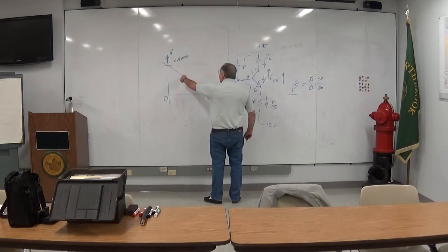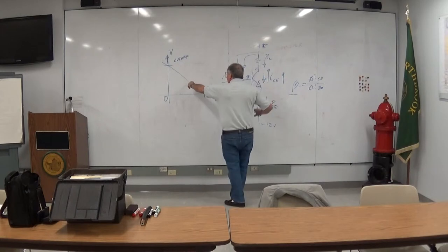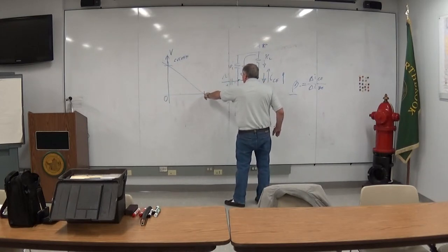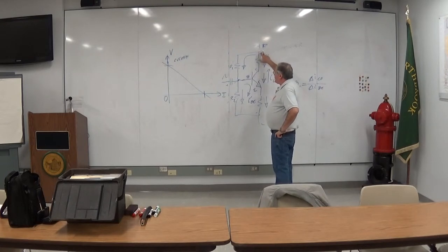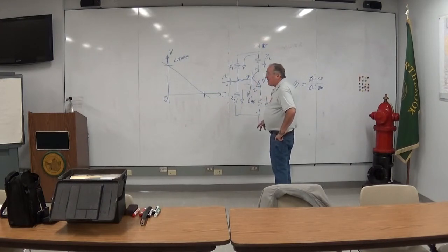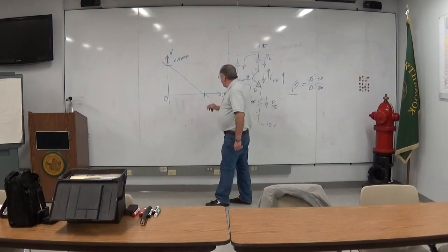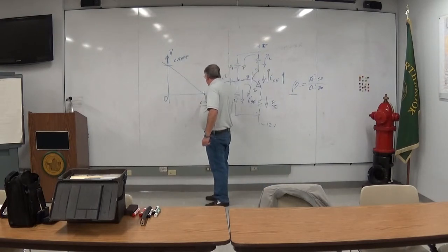So let's say I keep feeding more current in here until, essentially you move from here and the voltage across here starts to drop because the current's going up, and finally it hits a point where at the voltage I've given this thing, the voltage here is zero. I mean, basically this thing is wide open. If I feed more current in, the voltage can't get any lower. You really hit a rail here. This thing is called saturation.